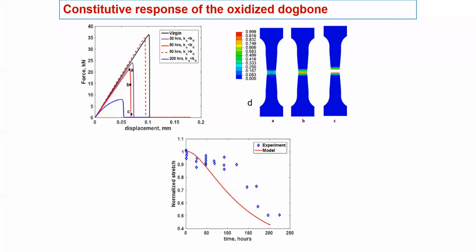But for the crack, if you actually give it a finite width, you can directly write a variational fracture formulation. You calculate the energy dissipated over that finite width of the crack and add it to the total energy, and then just minimize to get how the constitutive response for damage or stress will be. So that is actually an advantage.